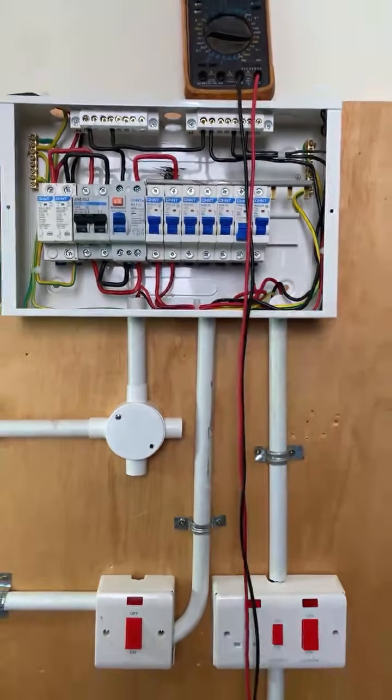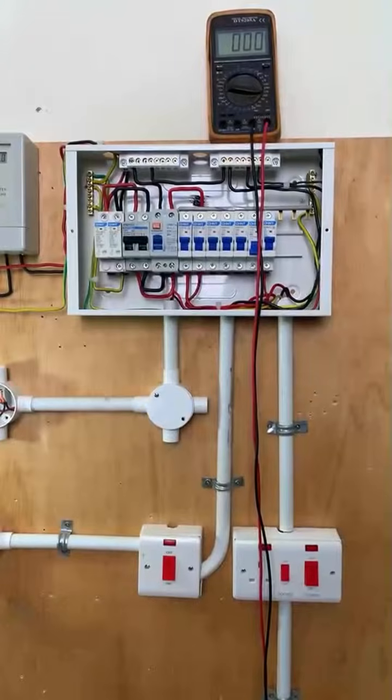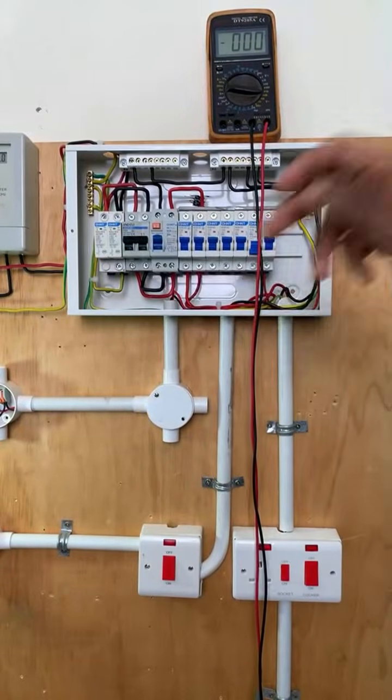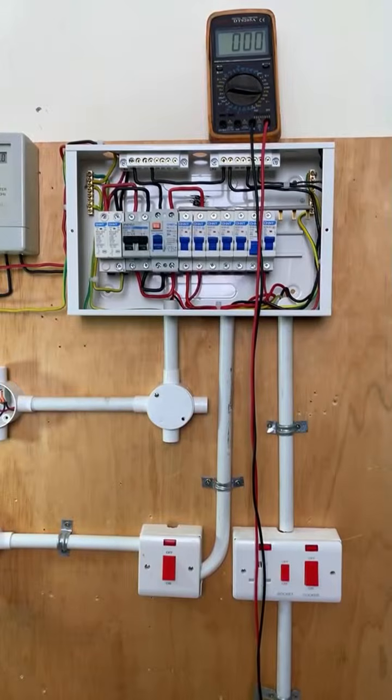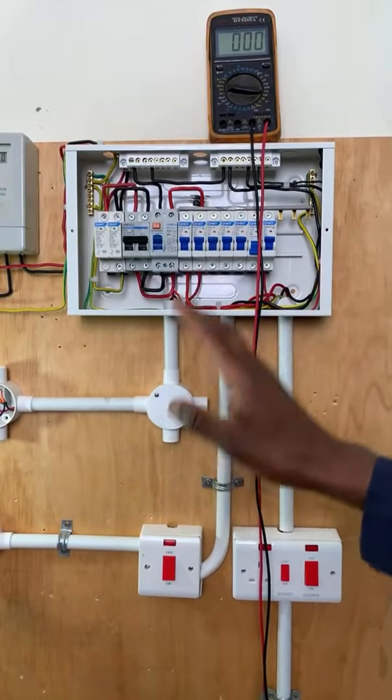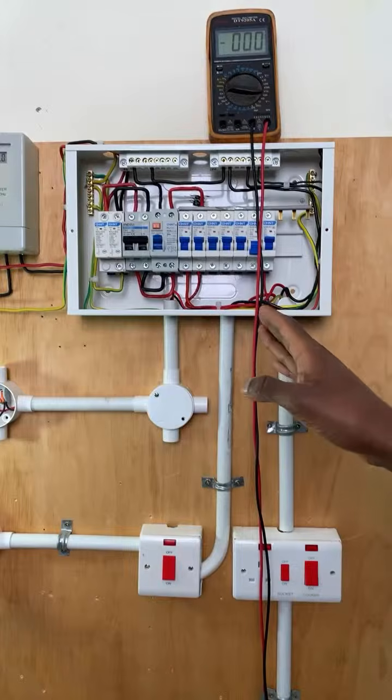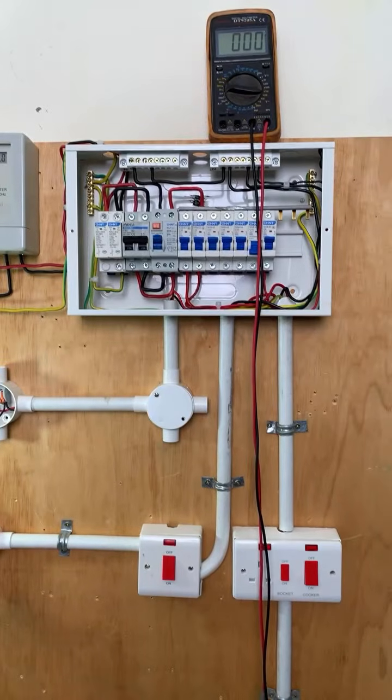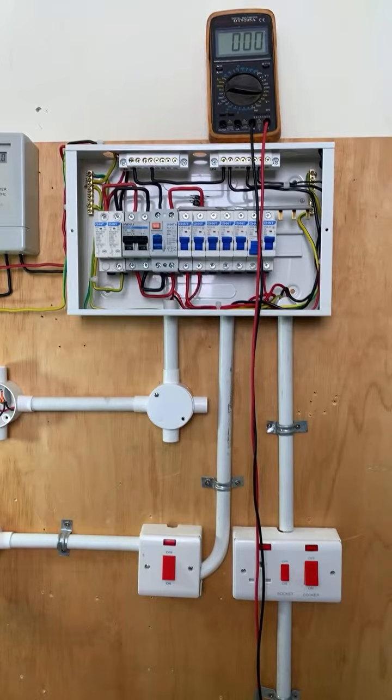So we expect our readings, and especially for that circuit, our question will be, maybe the customer has said that there is a socket for the washing machine, it is not working. You have gone to the consumer unit. Why go to the consumer unit? That is simply because the consumer unit is the heart of any electrical installation. And for any problem, you expect to have a consumer unit fault that is a tripping MCB.